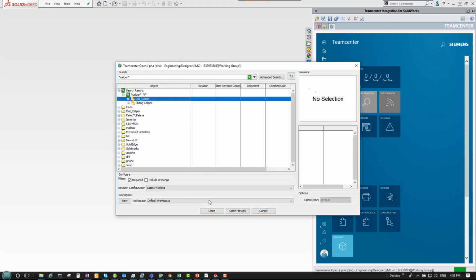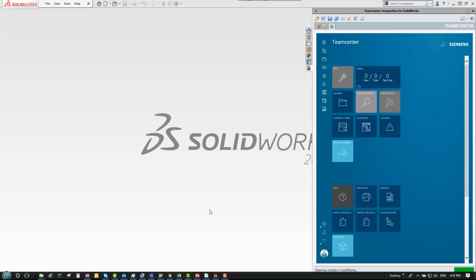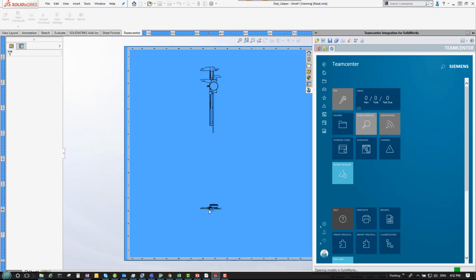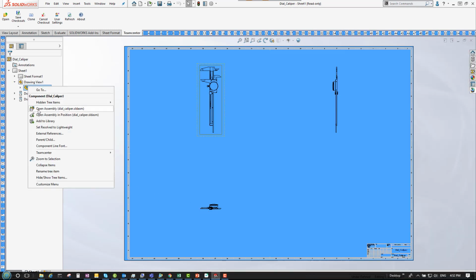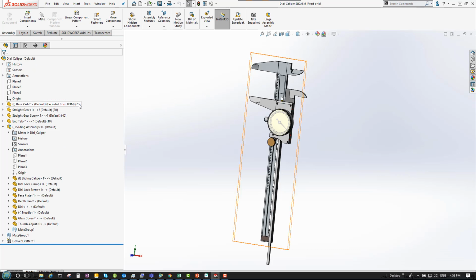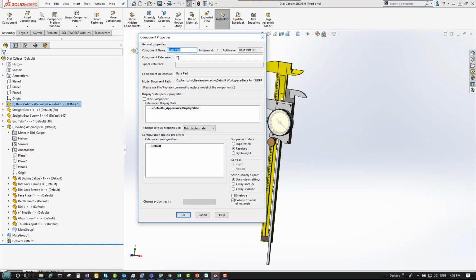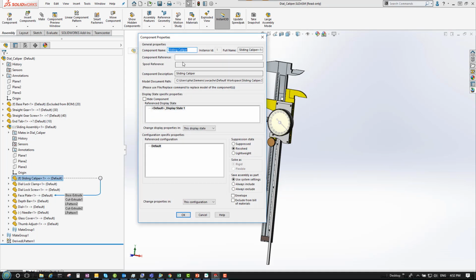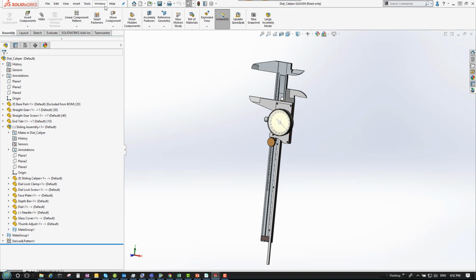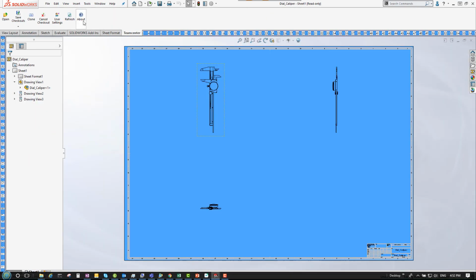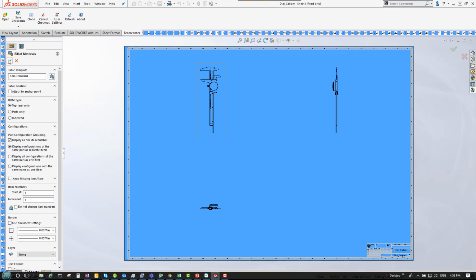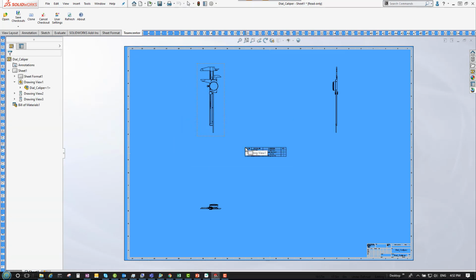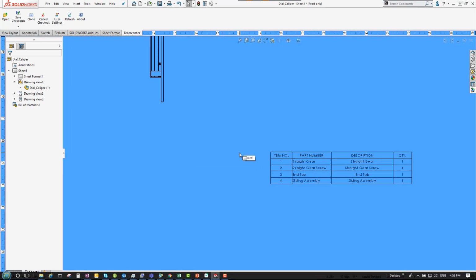Any Teamcenter bill of materials property can be mapped to the SolidWorks assembly model tree, for use on tables and annotations. In previous releases, this mapping was done at all levels of the assembly. Now, in version 12.1.0, the mapping is performed, by default, only at the top level of the assembly. This is aligned with other Teamcenter integrations, and with SolidWorks itself, in the way that BOM tables are placed on drawings. For large assemblies, it can yield significant performance improvements. Full top-to-bottom mapping can be restored, if desired, by a new preference in the Properties file.